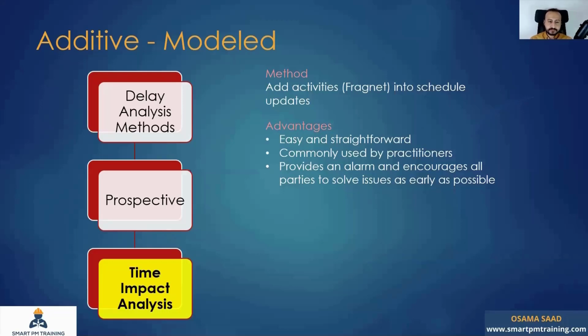For example, in the fragment, say there is one variation order. And in your fragment, you accounted for 2 weeks to prepare a new material submittal, followed by 2 weeks for the engineer's review. When a client reviews the fragment, he will see, for example, 2 weeks. So if he can force the engineer to issue the approval within 3 days only instead of 2 weeks, it will give you huge savings. And after the engineer's approval, you accounted for 3 months of material delivery.